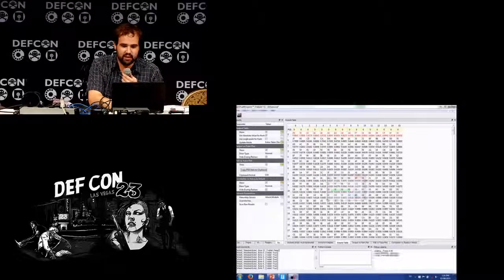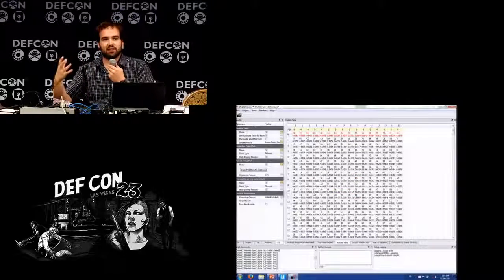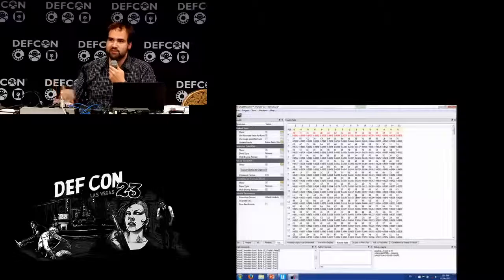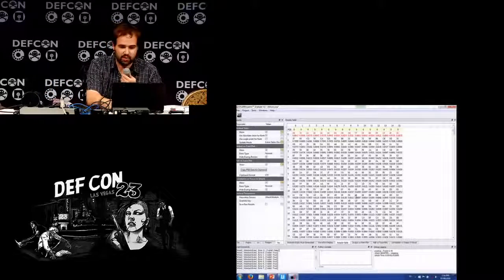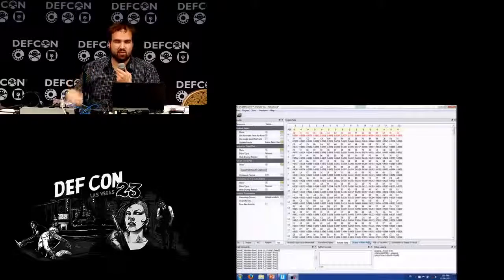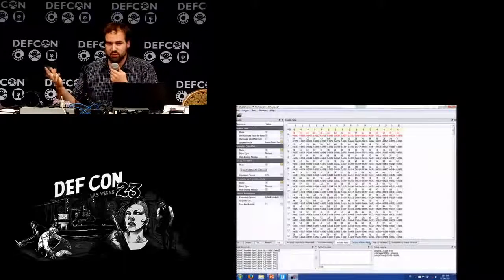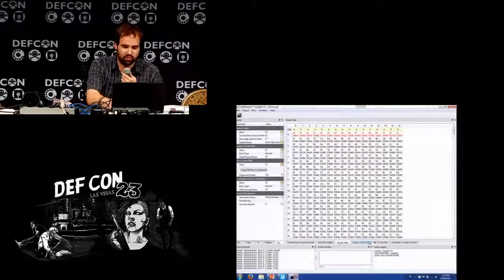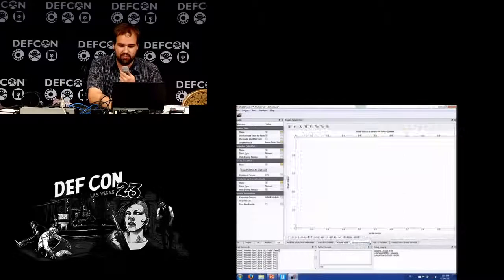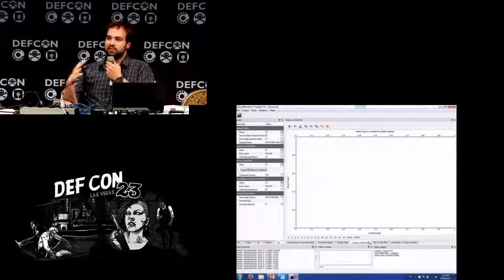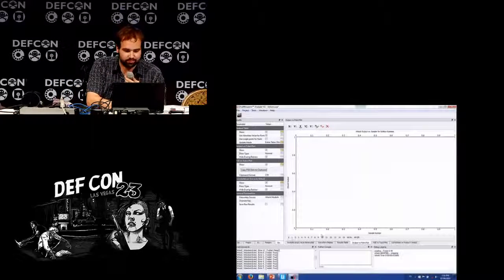So that's by sending like 30 packets to this device, doing the side channel analysis, it recovers the full AES-128 key. And that's using, I believe it was AVR CryptoLib, so it's an open source crypto library. It doesn't really matter which crypto library I use. If there's no protection against this stuff, it's going to be vulnerable.